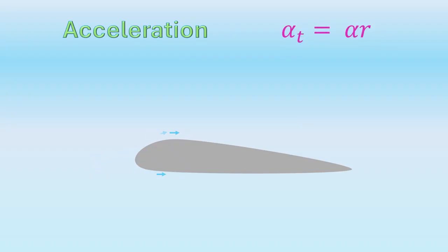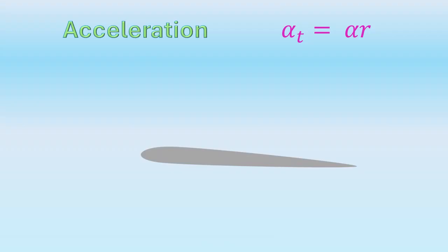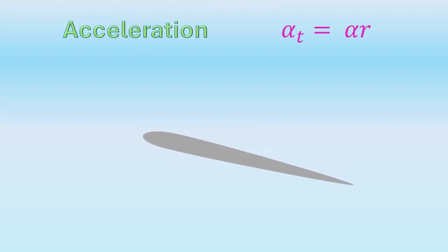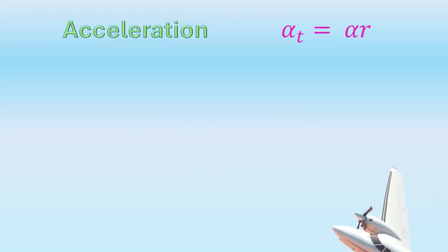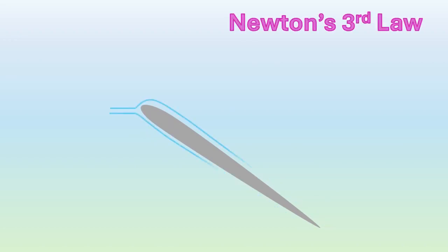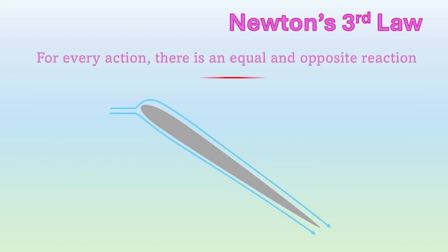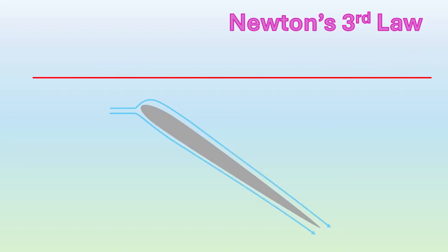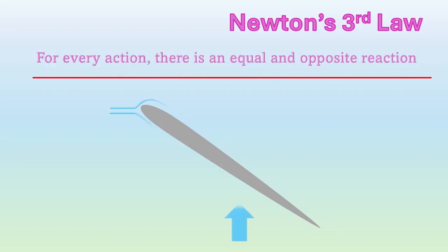In fact, the wing's upper surface doesn't even need to be curved to generate lift. The angle of attack works similarly to a curved surface. That's why airplanes use a high angle of attack during takeoff and climb. More lift is required during these phases of flight. When the angle of attack increases, air is directed more downward. According to Newton's third law, this downwash of air produces an upward reaction, lifting the airplane. This is another reason why a higher angle of attack is necessary for takeoff and climb.